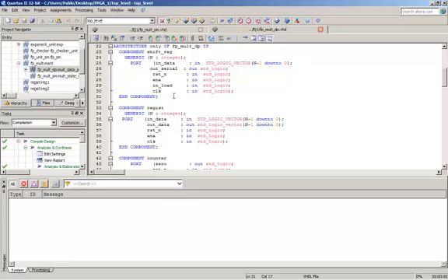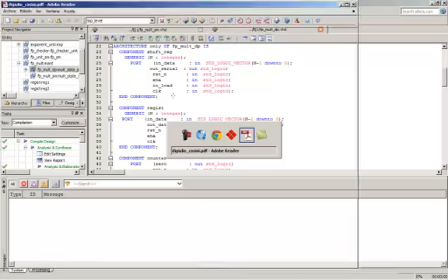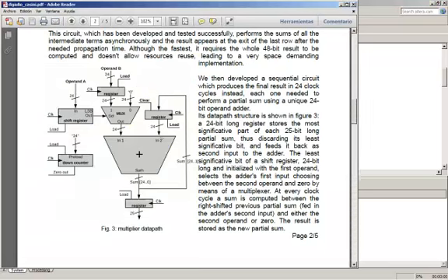I will show you the architecture that we use to implement the sequential integer multiplication. As we can see here, we have a huge adder. As we know, the multiplication of two numbers is a multiplication and addition, a multiplication and addition. So we have a huge adder that takes one operand from one register, and it could also be 0. The selection of the multiplexer depends on the other operand. As we can see here, we have operand A and operand B.